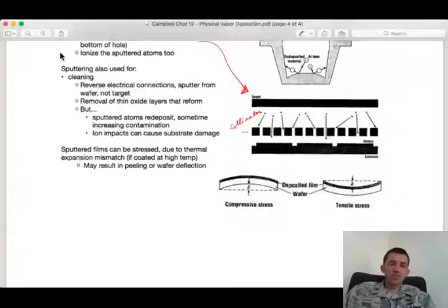And so, as if it needed to be any more complicated, right? You'd say, well, I heated it so that I get good step coverage, and then maybe the way that you heat it actually produces these residual stresses, which can cause other problems down the line. So everything has unintended consequences and knock-on effects, and just like anything else, it's more complicated when you actually get into it. But here we're just trying to introduce some of the basics. So that's all I had on physical vapor deposition.